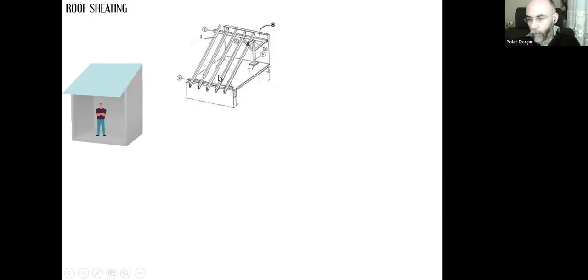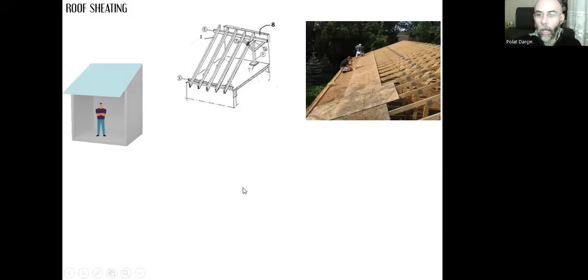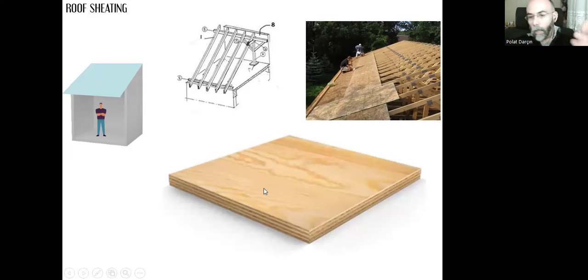If we want to place thin bitumen sheets over the rafters, the bitumen will sag. It won't be able to hold its posture. That's why first we need to cover the upper surface of these rafters with artificial timber planes, engineered wood panels. I think you remember we covered this last semester.